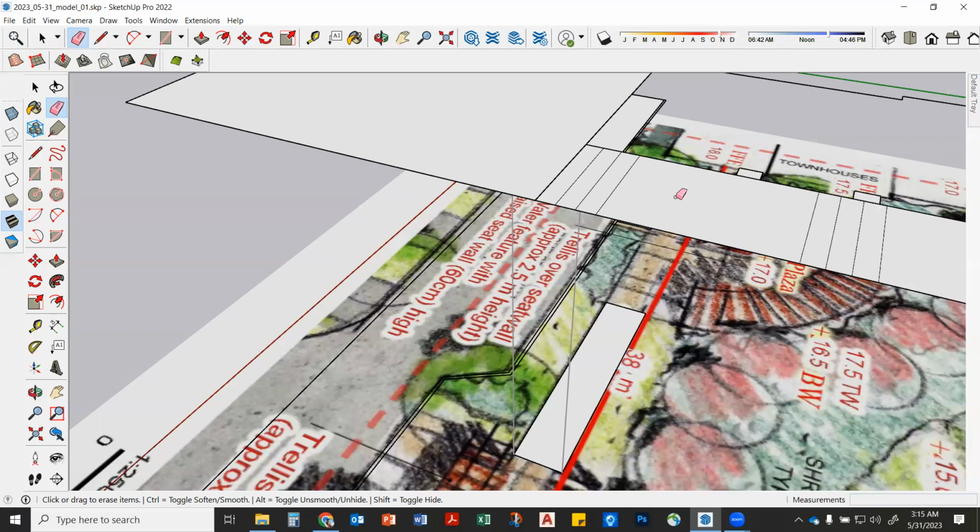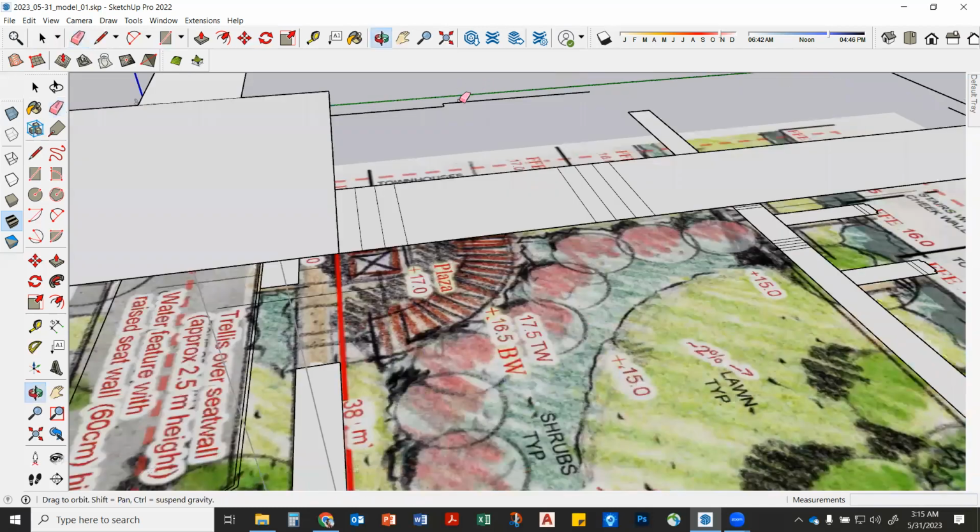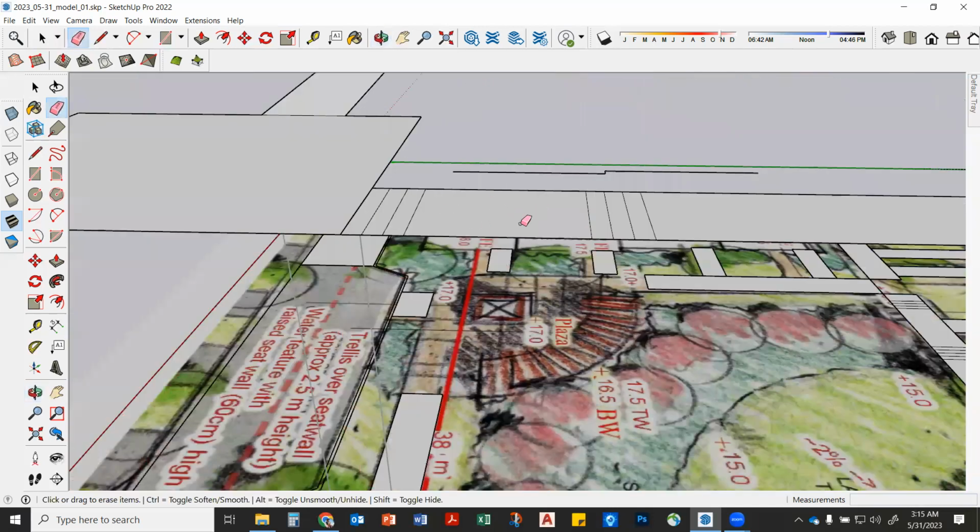So all my hardscape slopes a minimum of 1% in some direction, yeah? You'll see plenty of places where it doesn't do that, right? But you guys as professionals are gonna make sure you got 1% slope going somewhere, yeah? On all hardscape. That's a long kind of diatribe, but we can slope this thing right here a little bit and be okay, yeah? Remember that third riser, or that 0.3 riser we need? Maybe we can just slope this a little bit, yeah?